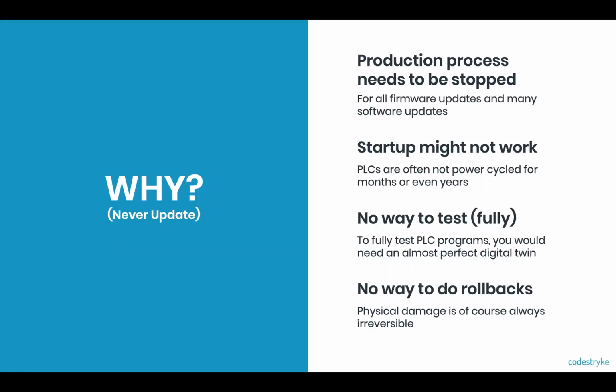So because PLCs are often not power cycled for months or even years, when you do power cycle them or stop them for an update, some of the time you lose important process parameters that you then will have to dial into again under time pressure to try and get the machine to start up again. And another problem is that usually you can't really test your PLC program or the new firmware beforehand together with